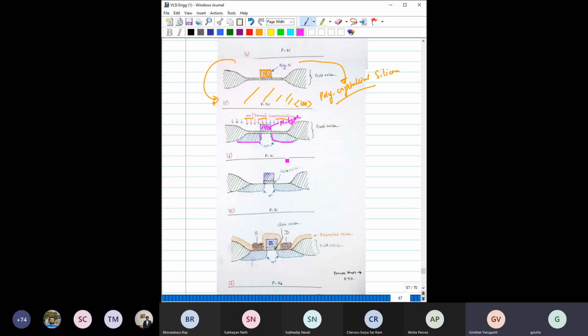So this gate line, you have to understand in a 3D view. So this is this gate pattern, right? If you are connecting some potential here, if the resistance is high, then this is the resistance and this is the capacitance, right? So this resistance also plays an important role in determining the RC delay.